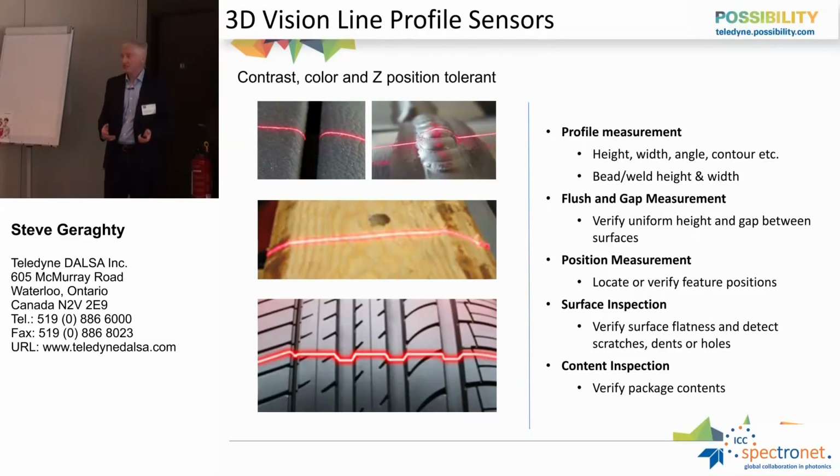These products can also be used as a camera, because in some applications it's not convenient just to look at the profile. You want to look at the whole surface, right? So what they can do is output these profiles very fast and have them caught by another embedded computer somewhere to generate a surface, and that surface can be inspected with 2D tools. So for example, this weld application where the height varies and the width varies quite a lot. If you want to look at the porosity of the weld, for example, these are the holes in the weld, you might be better off doing that with 2D tools than a 1D profile. So the camera could output a surface for you and you can use 2D tools on that.